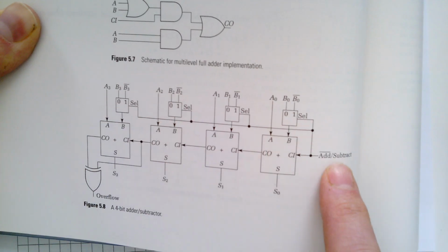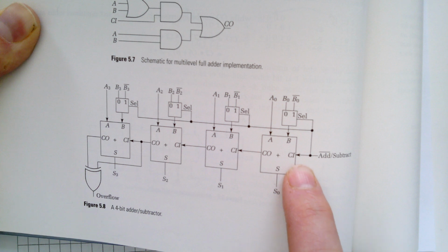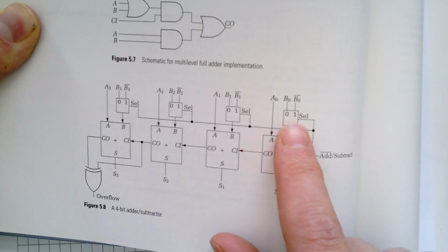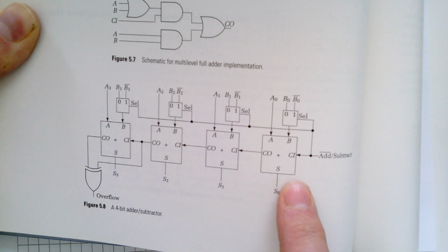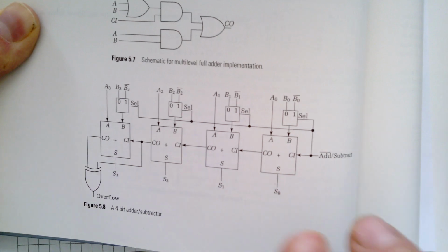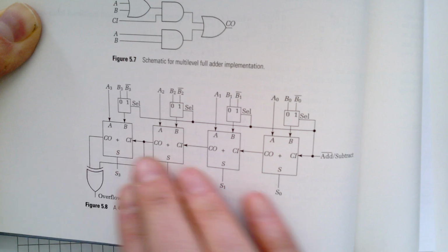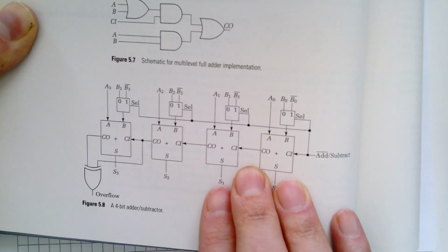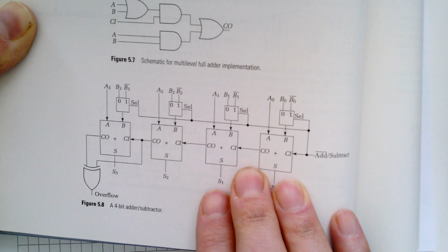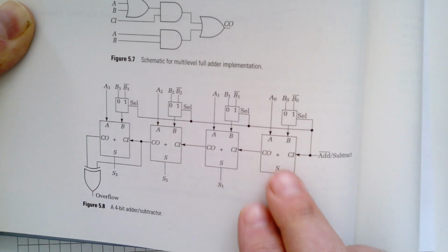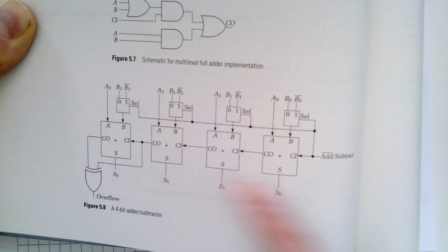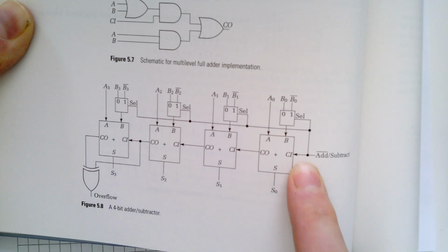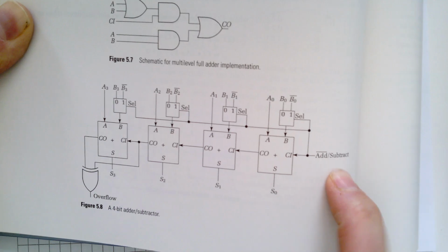And if you put the 1 in on carry input, it's going to increment the accumulator. In other words, this is doing complement and increment. And as a result, it gives you a way to leverage the existing full adder hardware in order to be able to do subtraction. So it's a twofer. You get to add and subtract all with the same full adders. All you need to do is find a way to complement the variables and provide for a carry in. And all you need to do that is to assert the subtract line.